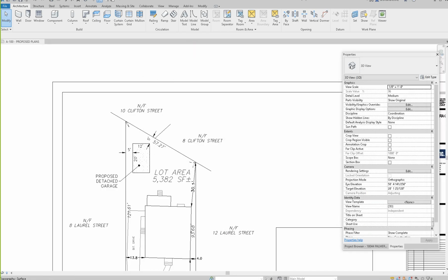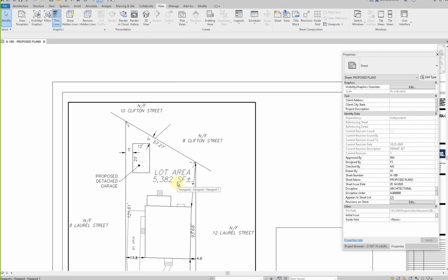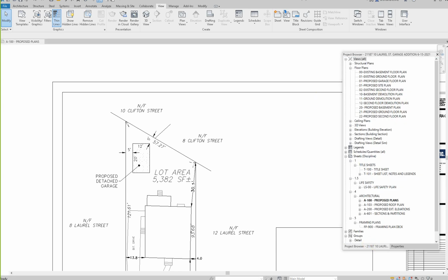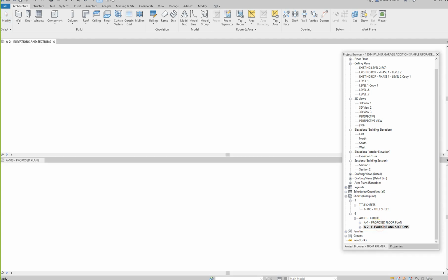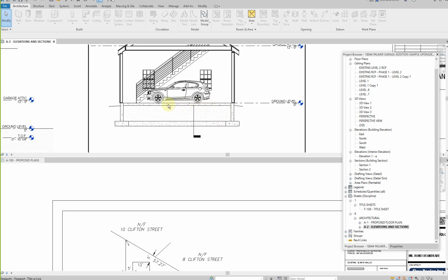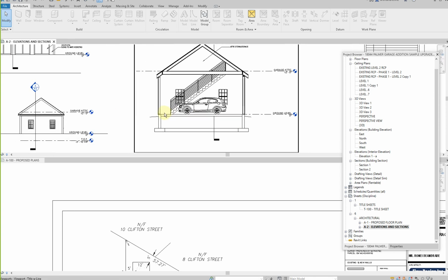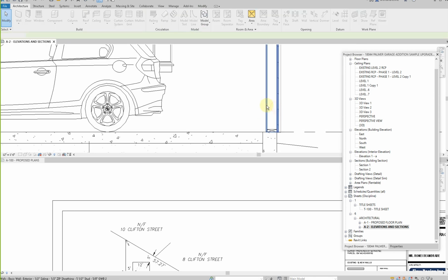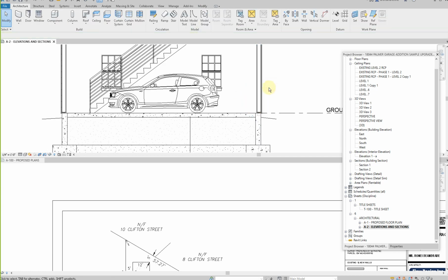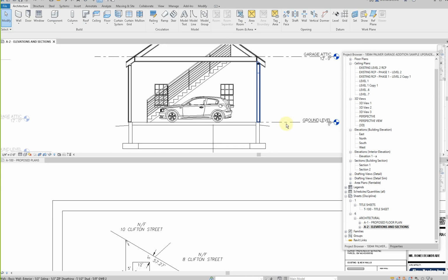All right. But I also like to think about what wall type it's gonna be, how it's gonna be. So typically, garages in New England are like a slab on grade. Let me see how I can explain that to you. So typically garages are like this. They don't have a basement. They have a concrete slab and a concrete footing, a frost wall they call these ones. And that's it, right? And typically they're out of 2x4s. They don't even have sophisticated walls or anything like that. This one is not even insulated right now, but I think I'm gonna do a little nicer than that.